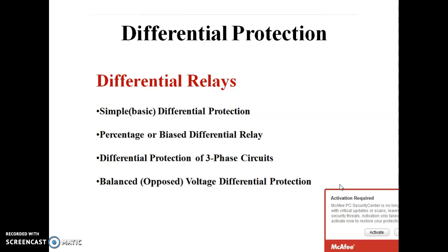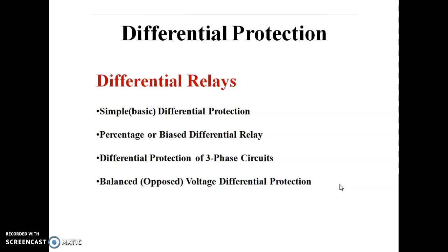It is the most sensitive and effective method for this protection. The main principle is detecting very small magnitudes of the differential currents. The disadvantage is that it requires currents from the extremities of a zone of protection, which restricts its application to the protection of electrical equipment such as generators, transformers, motors of a large size, bus zones, reactors, capacitors, etc.